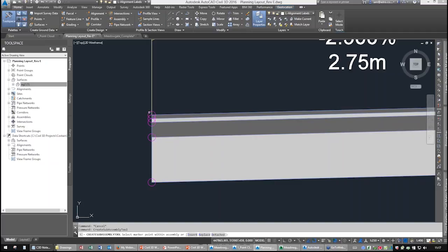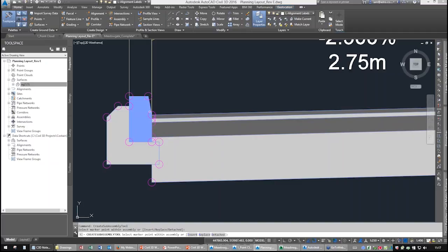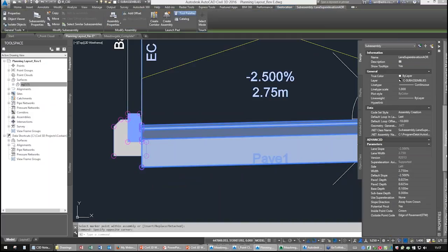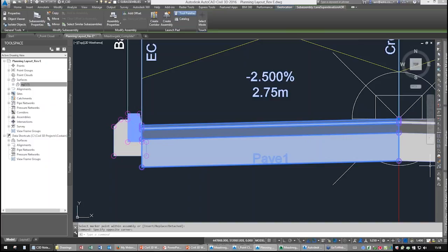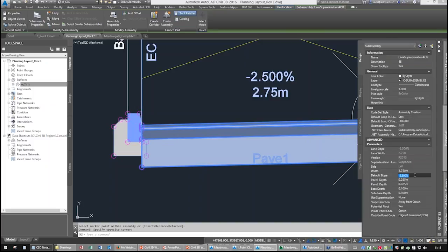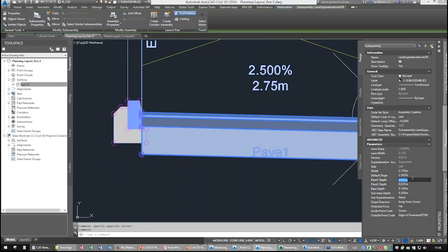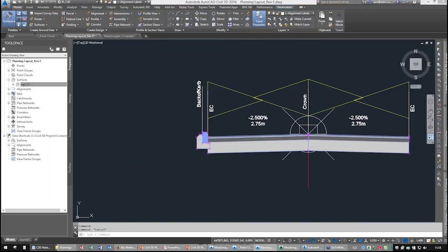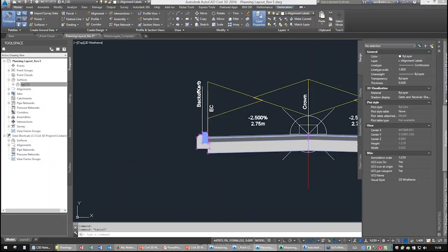These are anchored, and it's important that they are attached to it, because if I change the elevation or the width of this lane, I want that to move with it. So it needs to be anchored to it. So that's why you've got to select the little cyan jobby. So if I change that to 2.5, you want the curb to go up with it, of course, which it does.